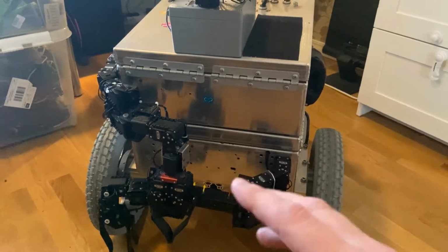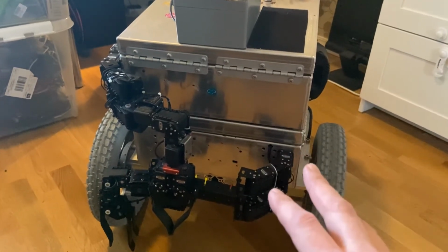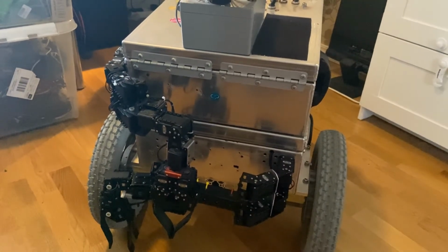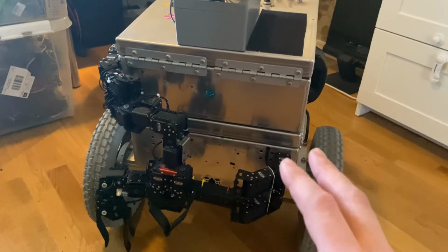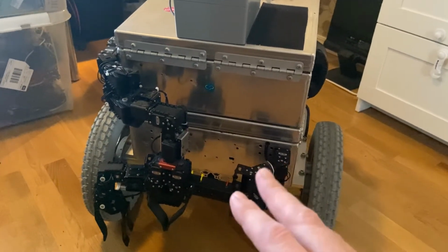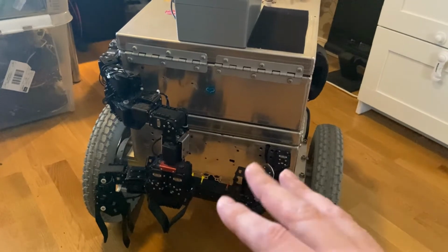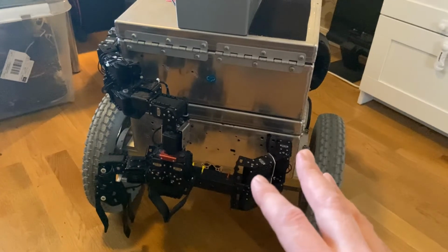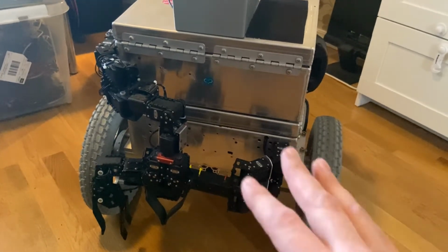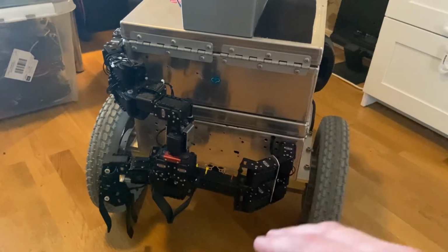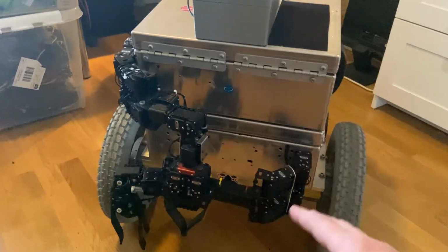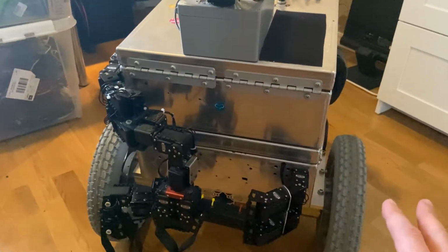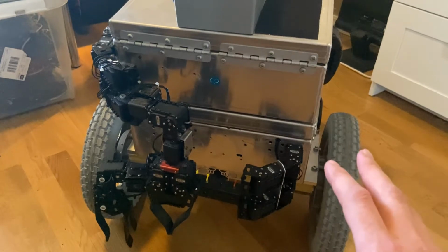I tried ROS 2, but it's too early in development with so many problems that I just decided to skip it. Instead, I decided to use another commercial data transfer protocol over Ethernet, which is supposed to have much smaller latency. I know some other software and equipment that already use it, so I had experience and it seemed quite good. So I implemented that on the Raspberry Pis in each of the actuators and units and removed ROS completely. And it actually works very well.